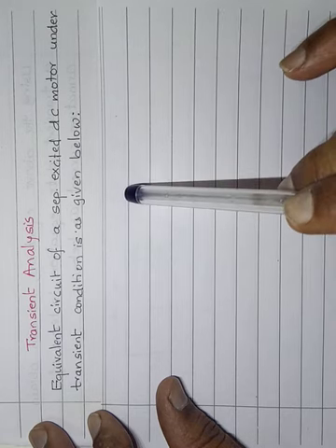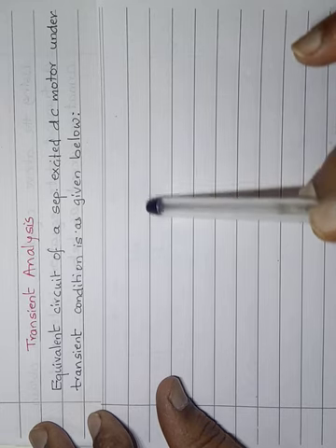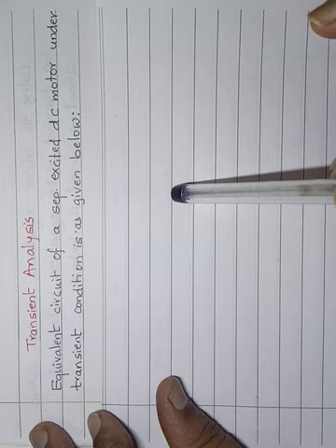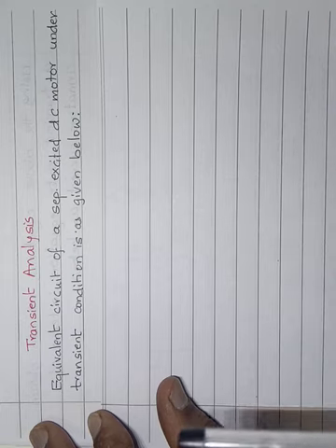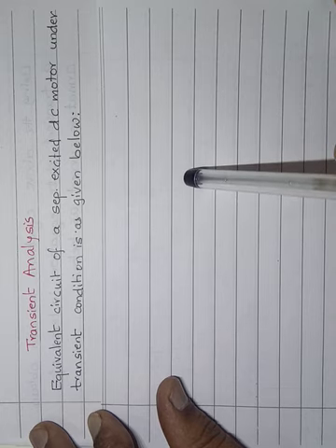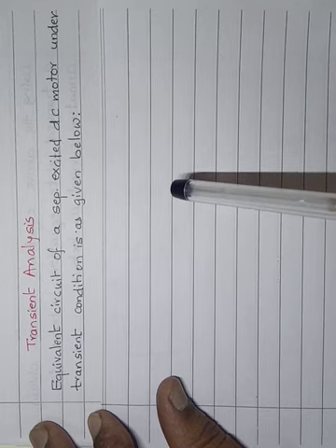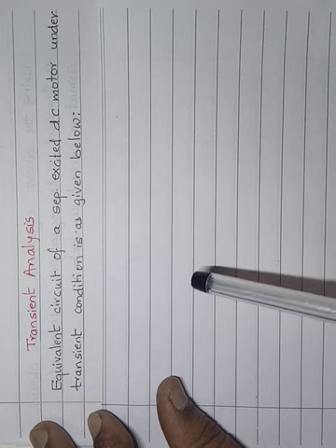I repeat, in the armature we had supply voltage, we had armature resistance, we had EB back EMF, whereas in the field coil we had field circuit, we had supply voltage, and field coil having a resistance, maybe we can call it RF. Are you watching carefully the parameters I am mentioning? There I mentioned only RA here, RF here on the field side. I did not mention the inductance because that time the analysis was steady state.